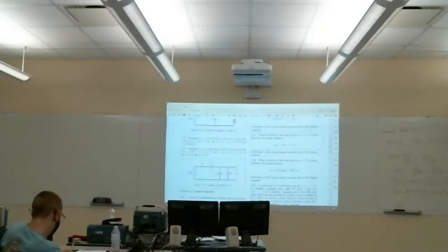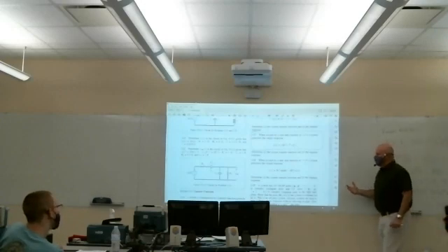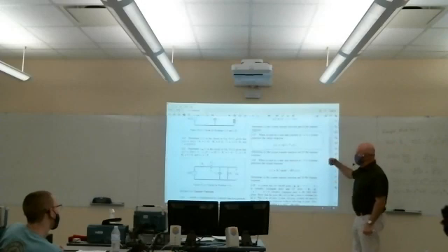This impulse is located at t equals 0. If I evaluate this at t equals 0, because of the t squared term, that's 0. That's not always the case. If this t squared weren't there, e to the 0 is 1, this would reduce to 10 delta t, but it wouldn't go away. But because of the t squared here, this is 0. It's 0 delta t, or 0. And so it matches. So in this case, it's actually easier to find the derivative of the step response.